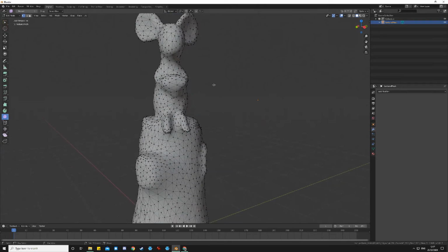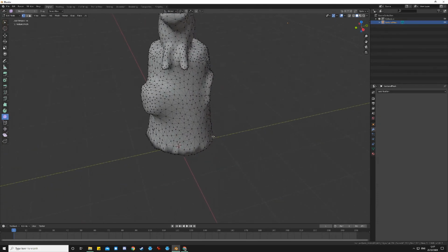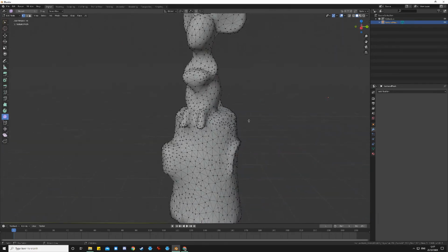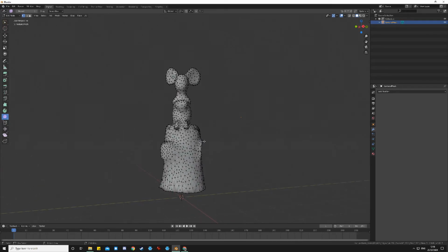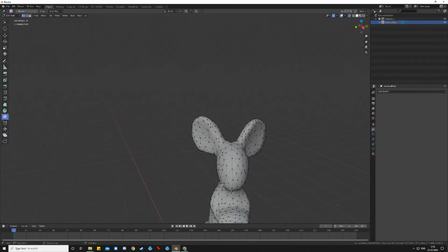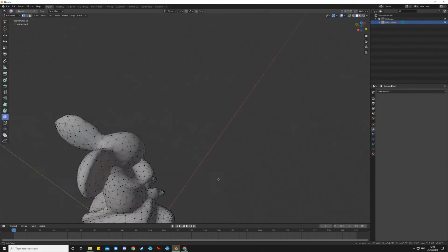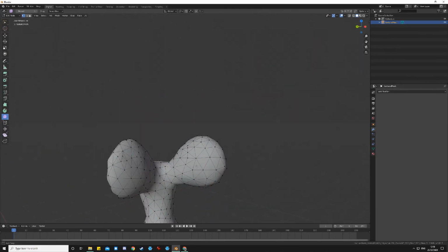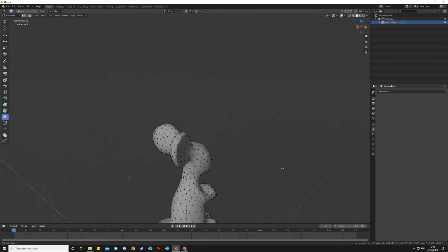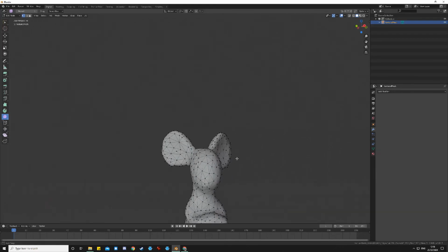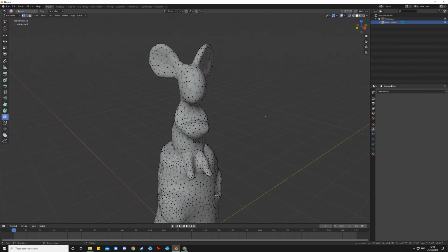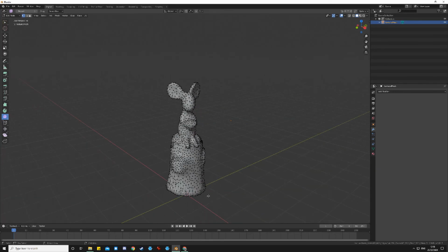Sometimes I do a subdivide, where I divide all of the polygons up by one more, so it almost doubles the amount of polygons, and then smooth it. You should get less geometrical fiddling with it then. But I don't mind it being a bit smaller than the original mesh, so that we can actually fit it within. And actually, if you look at those ears now, they look really good. They don't look like there's chunks missing out of them anymore. And yeah, some of the detail on his arms has gone, but the texture is going to do a lot of that work for us.